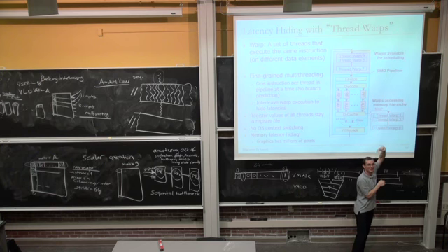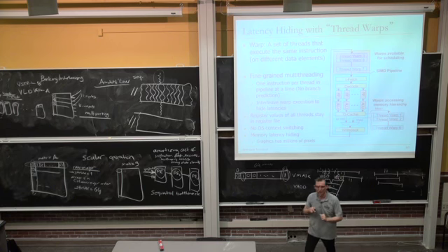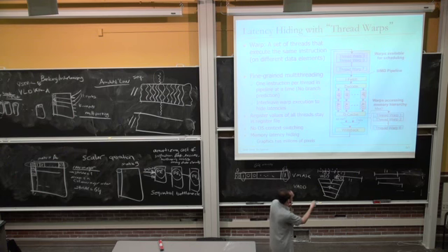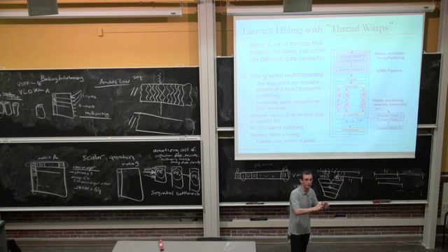So is the scheduling of that all handled by the hardware, or is it software? Yeah, at least this level of scheduling is handled by the hardware. And existing GPU hardware does things like this, basically. If one of the threads in a warp is stalled, why don't we regroup the threads in different warps such that we can continue execution fast?